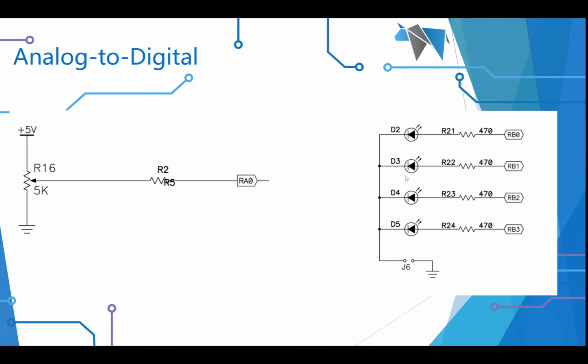So zooming in on what we're attached to, let's get the right-hand one done. LEDs through suitable resistors are connected to ports RB1 to RB3. 4 resistors, 4 LEDs. And on the left-hand side, we've got RA0 connected. It has a current limiting resistor, and then it has a potentiometer, a 5K resistor. And as I change the voltage on that, or the position of the potentiometer, the LEDs will react. And how will they react?